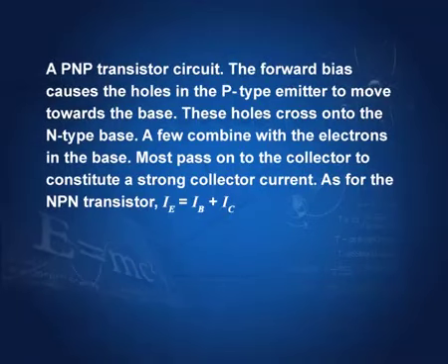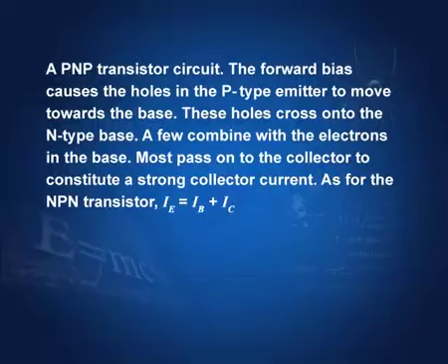We saw in the last lecture an example where we found the drift velocities of electrons and holes, and we found the electrons move faster. So holes are a little sluggish, and in the PNP transistor the motion of holes constitutes the current. Therefore the holes move a little slower, and at higher frequencies you can have some problem. Therefore, at higher frequencies the response of PNP is not as good as the response of NPN transistors. So for high frequency applications we prefer NPN transistors.